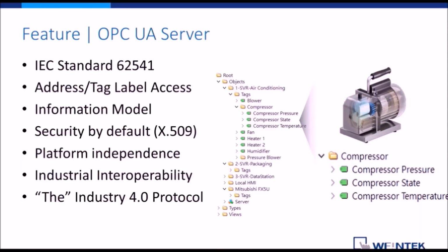So other things, on top of the address space, the OPC UA has an information model concept, which builds on top of the address space. I think many different industries are building their industry-specific information model, like Euromap for injection molding machines. And for the gas and oil industry, they have their own information model, and they can apply it to the address map that you see here. So as we go down, we understand that when we're dealing with the industry, we know what tags we'll be dealing with, and we don't worry about whether we are missing some data or not.